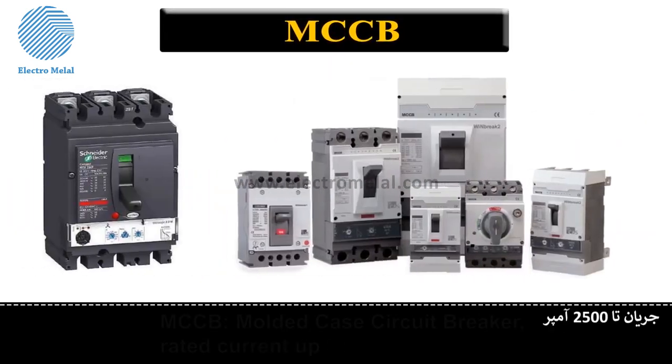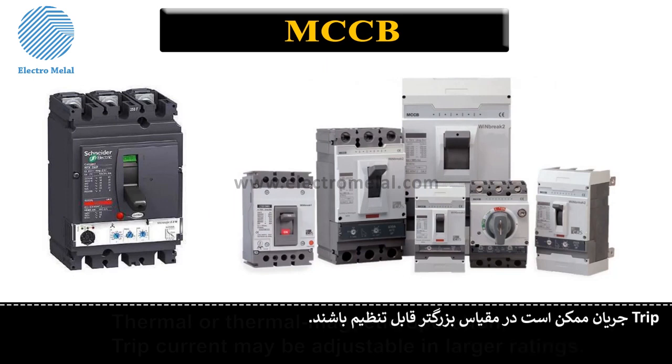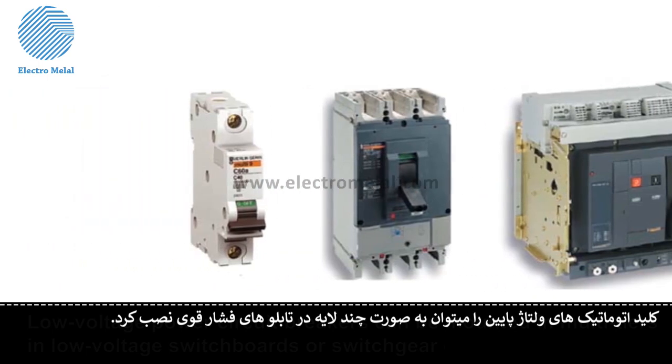MCCB, molded case circuit breaker, rated current up to 2500 ampere. Thermal or thermal magnetic operation. Trip current may be adjustable in larger ratings. Low voltage power circuit breakers can be mounted in multi-tiers in low voltage switchboards or switchgear cabinets.